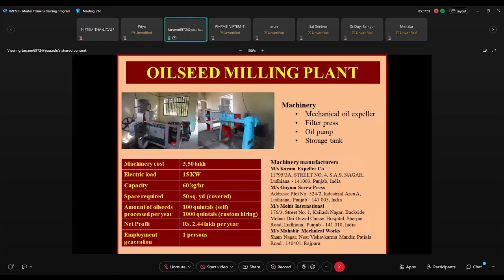So if we try to extract it with water, it's not simply possible. If we are using some chemical method or solvent extraction method, then we have to use petroleum ether or hexane for their extraction. But that is not feasible at the farmer's field, because the petroleum ether or hexane used in solvent extraction techniques are highly inflammable and cannot be controlled at the farmer's field. There are a lot of complexities involved, and a lot of processes are involved again to separate the edible oil from that solvent. Ultimately we have to separate the solvent from the oil which is to be used.